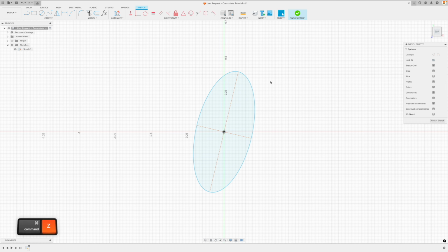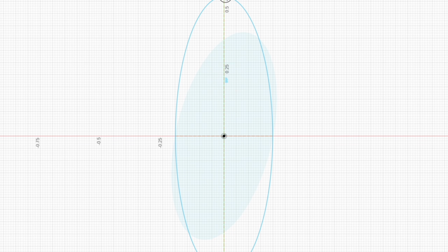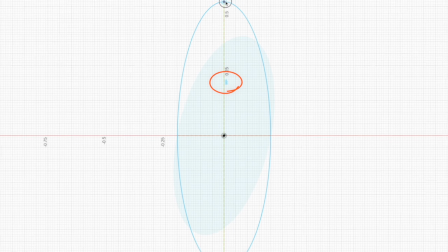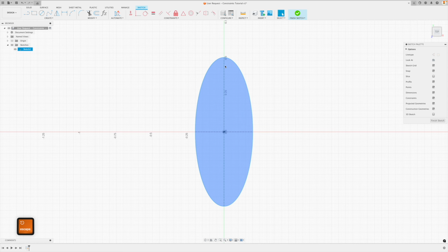But I'm going to show you one other thing. Sometimes this frustrates Fusion users to no end, but you'll love it once you understand what's happening. If I grab this line and make it vertical, look what symbol automatically shows up. See if I can bring it up here. No, it's not letting us. I just saw it. It disappeared. Okay, now it's dancing all over the place. There we go. Do you see the symbol right below the 0.25? There is our vertical symbol right there. It's beautiful. So I've just locked it in. And now this line can only move vertical. I can no longer move it. Oh, I've just broken it actually. There we go. What happened? There we go. It didn't actually show up before, but now it does.